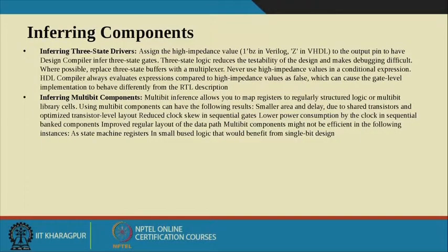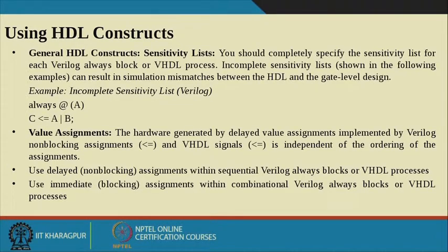So with or without control signals I can infer. Then again I can infer 3-state buffers, and I can infer multi-bit components. All these things I can infer by writing them in the HDL code in Design Compiler, using an HDL construct.